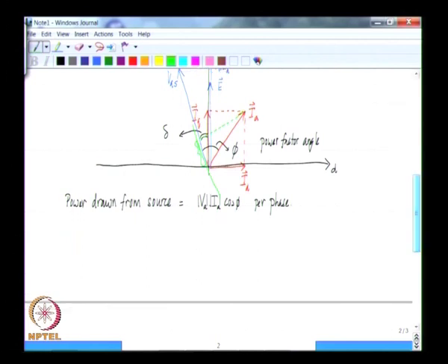So, now instead of looking at this length, another way of arriving at this length will be to consider ID and IQ, these two components. So, IA into cos phi must be the same as the sum of these two projections on this line. So, we can write this in turn as VA multiplied by, now look at ID.